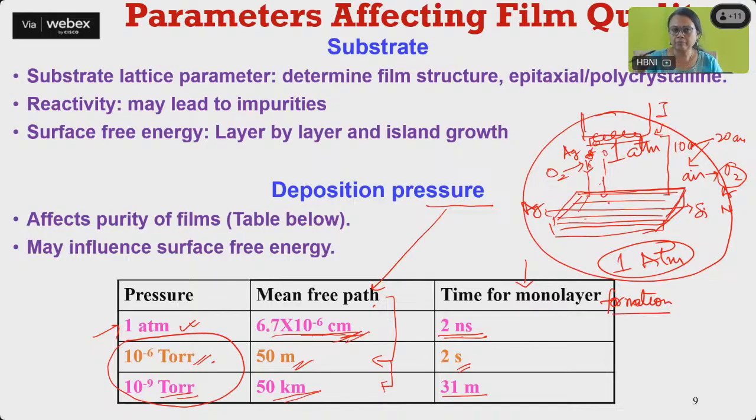So when I am depositing it, you can think of 1 atmosphere as like putting some silver in a beaker or alumina crucible and heating it. Do you think that if I put a substrate on top of it at 10 centimeter, you will get a proper thin film from it? No. A lot of evaporation will obviously be there, but it will be contained only in whatever vessel, the crucible, in which it is kept, and it will get deposited there, but we cannot have a uniform thin film.